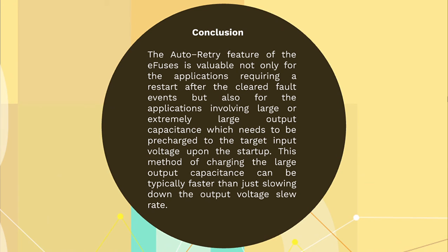Conclusion: the auto-retry feature of the eFuse is valuable, not only for applications requiring a restart after the clearing of fault events, but also for applications involving large and extremely large output capacitance which needs to be pre-charged to the target input voltage upon the startup. This method of charging the large output capacitance can typically be faster than just slowing down the output voltage slew rate.